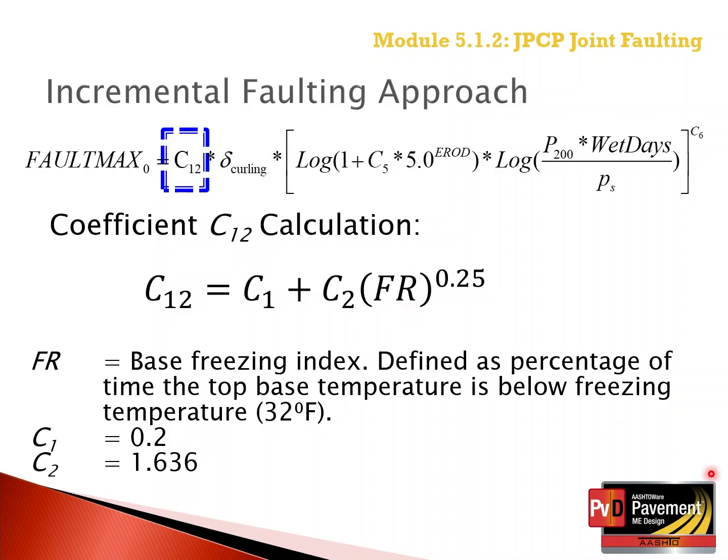The values for the calibration coefficients may vary between different publications of the MEPDG Manual of Practice depending on the results of the calibration. The coefficients and exponents of the transfer functions are also included in the output report for the Pavement ME design software.